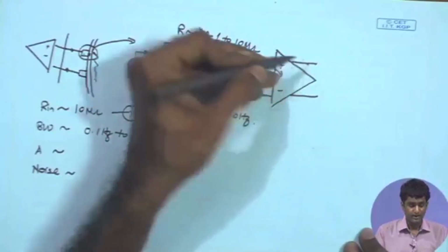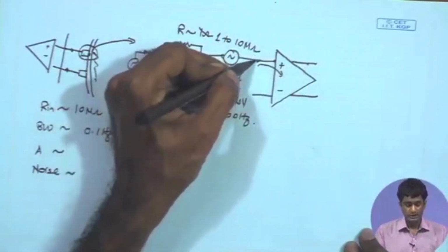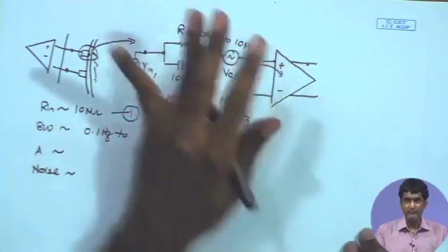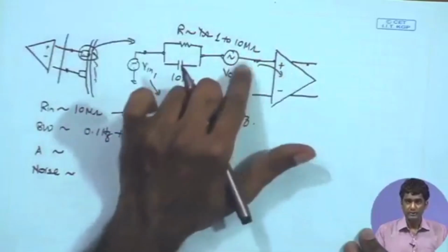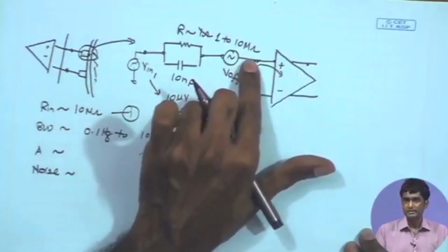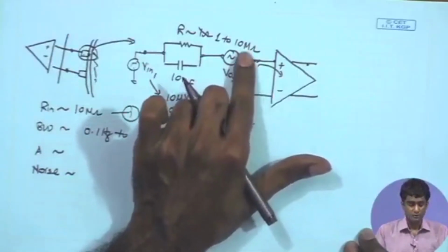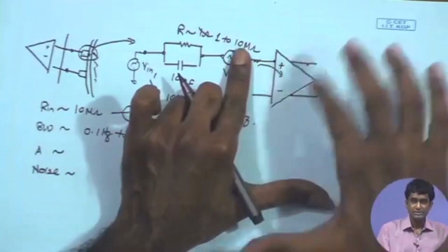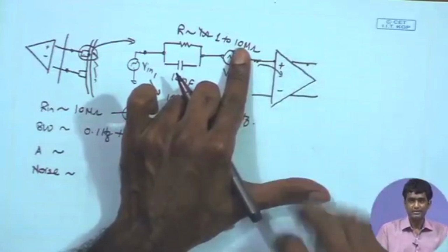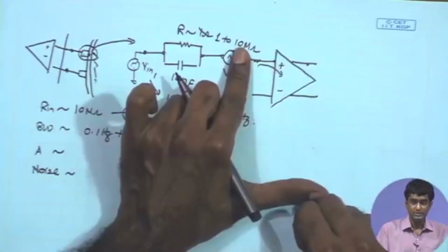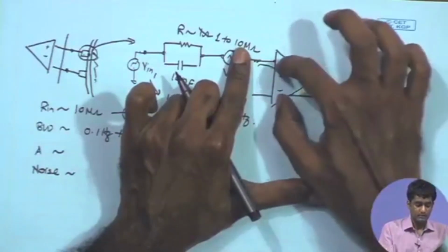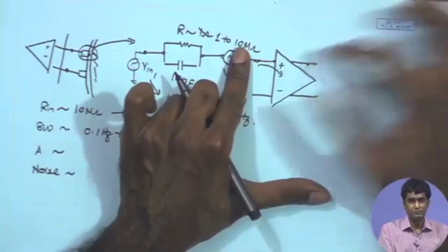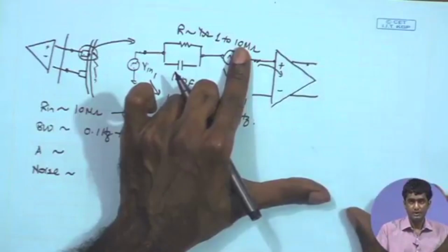So, how do we define the input referred noise? The total noise signal produced at the output in absence of any input signal divided by the gain of the amplifier can be seen as the input referred noise. So, when you do not have any signal applied to the amplifier, the transistors, resistors inside the circuit themselves are going to produce noise signals, noise voltages, because of which the output node over here will have minute fluctuations corresponding to the noise voltages.